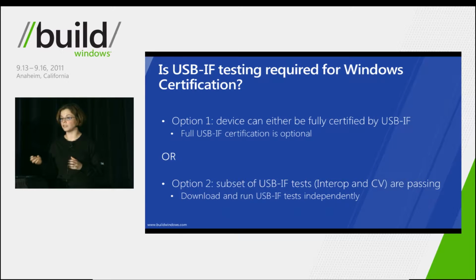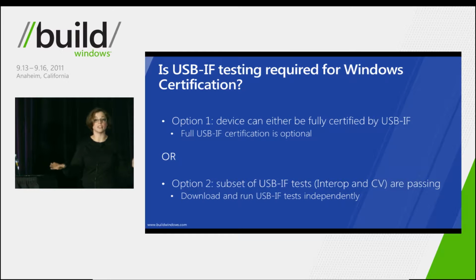However, from a Microsoft standpoint, we don't require full USB-IF certification. Part of the reason for that is we understand that it could be costly, and so for devices in particular, you have an option to just run a part of the tests that USB offers, which is the interop and CV tests. All controllers are still required to get full USB-IF certification because they are integrated into the systems and they do have to work with various devices. So it is important to get the electrical and interoperability and other types of tests that USB-IF certification offers.